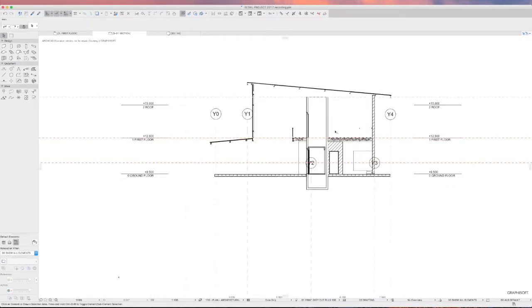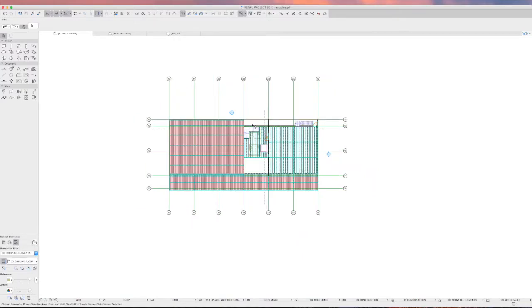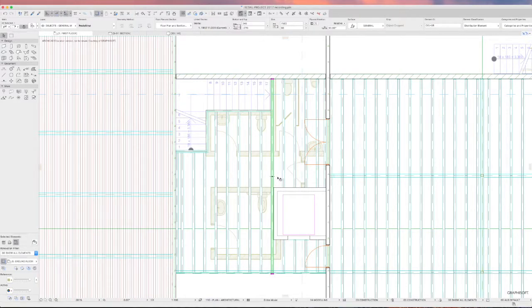And then once you get one of them set up to the right height, it's simply a matter of copying them around at 450 centres to suit your structural particle board flooring layout. So I think I probably started along the lift shaft here, along the outside of the lift shaft, to put the first floor joist in. Then I just went from there because that one ends up being very close to the top of the stairs anyway, and then we could just trim off the top of the stairs with a 45mm packer if we needed to, or a 45mm piece of timber of some sort.